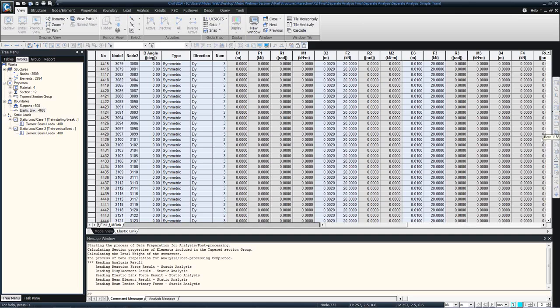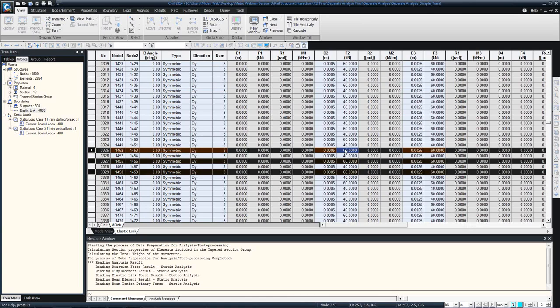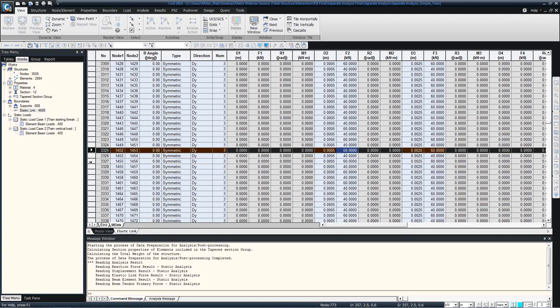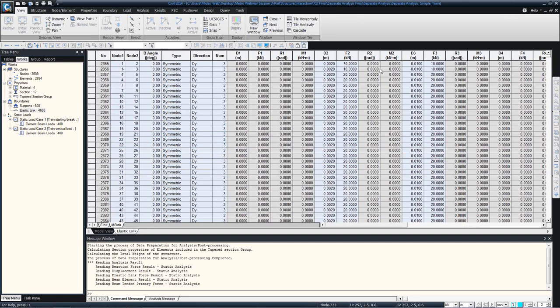So what we can see from here is that wherever the train loading is there, see the positions wherever the train loading is there, you can easily find out that it has taken 60 kilonewton as the, so because we have considered the effective length as 1 meter, so it has taken as 60 kilonewton as the resistance offered by the multilinear elastic link. Similarly, wherever the ballast bed is there for unloaded conditions, it has taken 20 kilonewton resistance. Okay, so these all things, just imagine if you have to input it manually, how much time it will take, because it has generated so many elastic links.